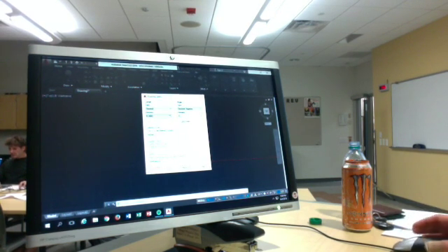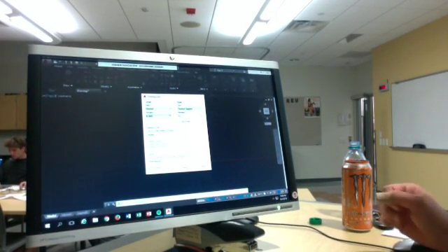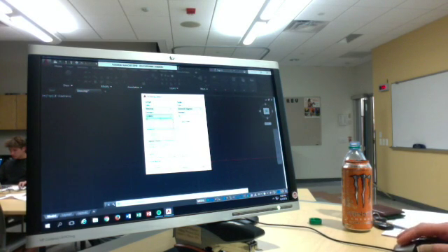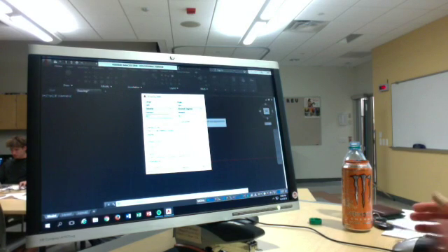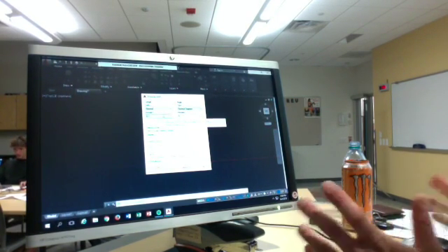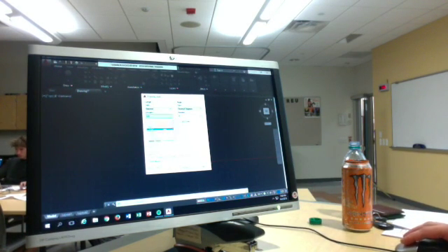If you're doing, let's say, some ductwork, well, you don't really need too many sig figs. Typically, you just do one decimal point. If, let's say, you're doing a high precision head for a drag car or something, you're going to have really tight tolerances, so you can put it up to 3 or 4 sig figs.